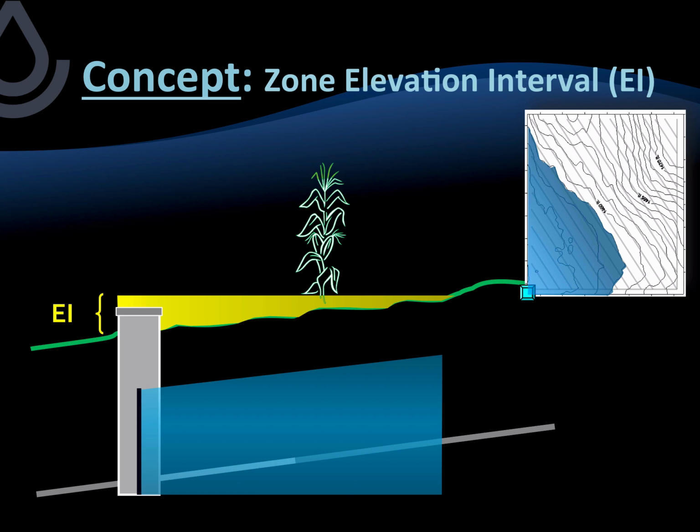Indeed there is. In fact, we know that water wants to seek a horizontal or level condition with respect to the land surface. And so what that means is that as we go back up into the zone, away from the structure, that is upstream or uphill from the structure, the water table is actually farther and farther off of our target depth, indicated by this red wedge here and the illustration in the upper right hand portion of the slide.